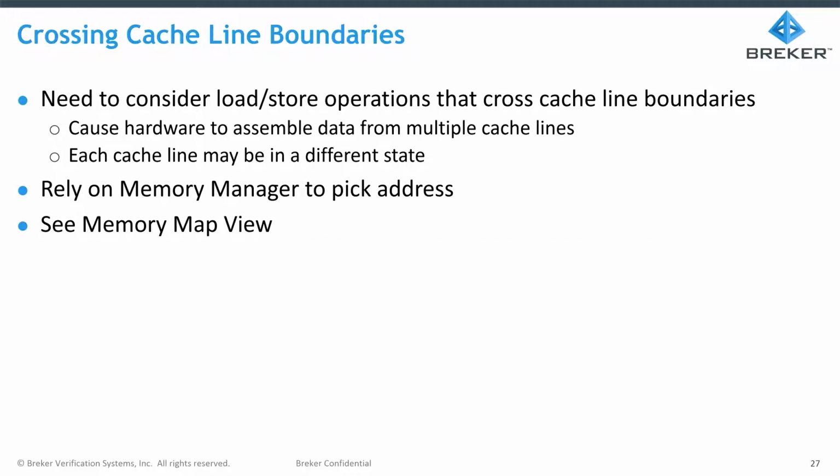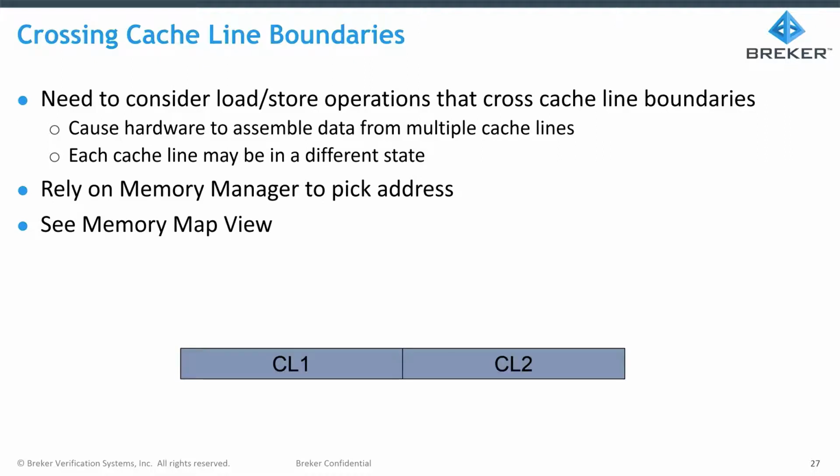Next thing we care about when we talk about cache lines is making sure that we can cross cache line boundaries. We want to do fetches that transcend the boundary of 2 cache lines. Often, those cache lines can end up in different caches, and hardware has to fetch both lines before the operation can carry on. So this is trying to show a little picture of 2 different cache lines and a store that hits on 2 lines.